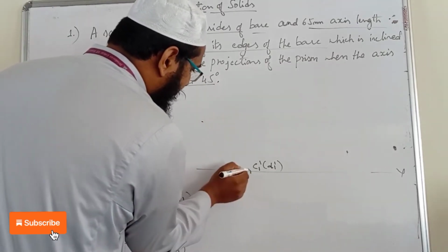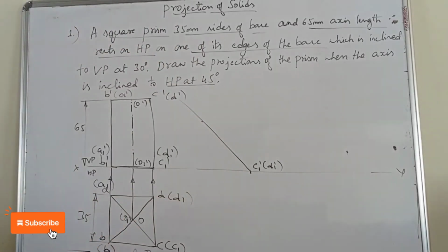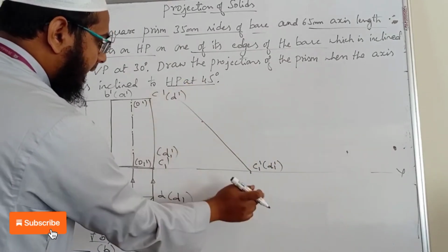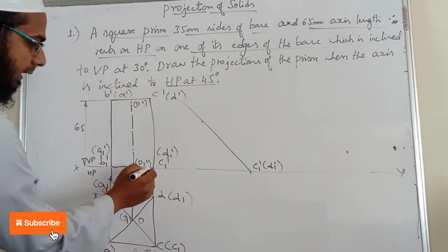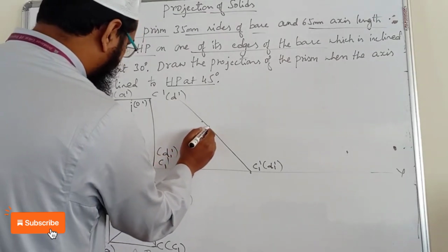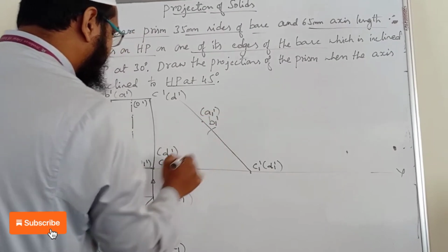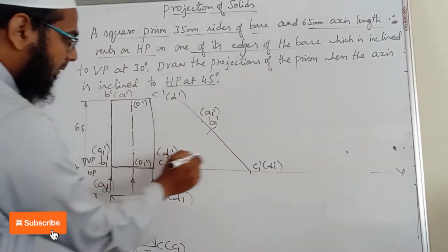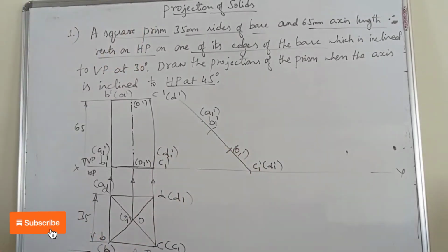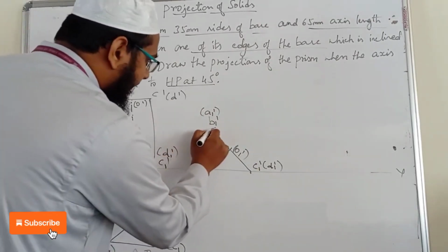Draw an angle line here. So that is for 45 degrees. After taking the reference point, keeping the protector, marking 45 degrees and drawing an angle line, next you have to take the compass and, measuring from C1 dash to B1 dash, cut an arc. This is B1 dash and A1 dash, and the second arc you have to cut from C1 dash to O1 dash. This is O1 dash. After cutting this arc, this is the length we require, right?